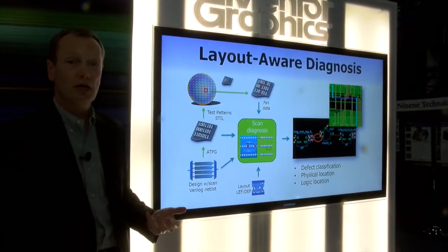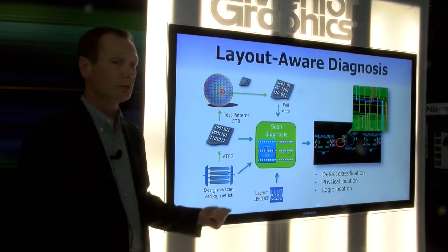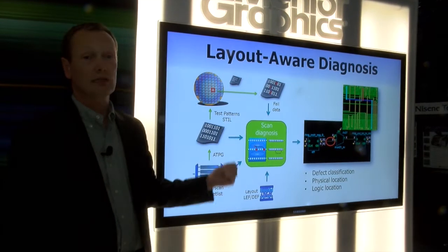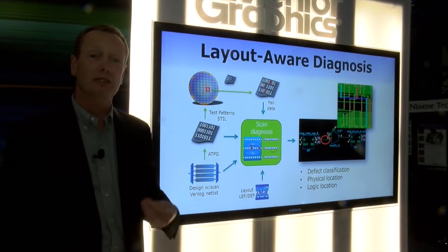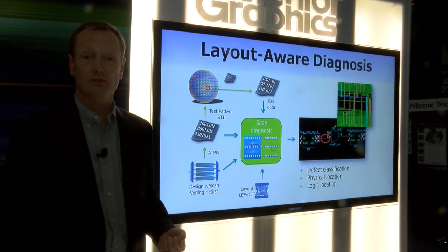And diagnosis is a process that leverages design description, both logic and layout design description, production test patterns, and fail data from the tester to identify the most likely defect types and defect locations that cause the devices to fail during test.